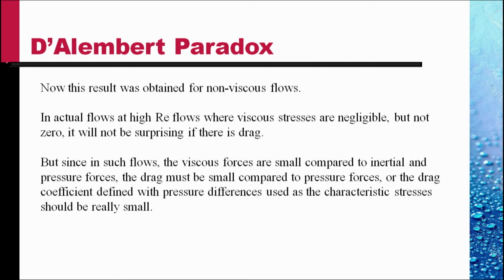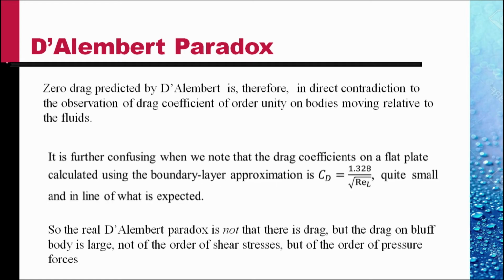But since in such flows the viscous forces are small compared to inertial and pressure forces, the drag must be small compared to pressure forces, or the drag coefficient defined with pressure difference as the characteristic stress should really be small. Zero drag predicted by D'Alembert is therefore in direct contradiction to the observation of drag coefficient of order 1 on bodies moving relative to the fluid.